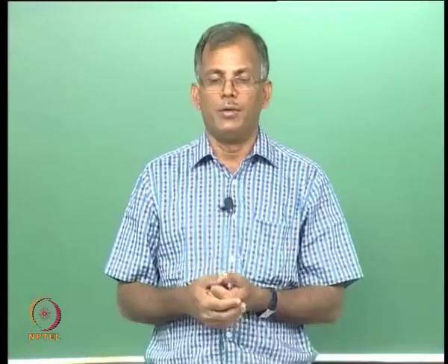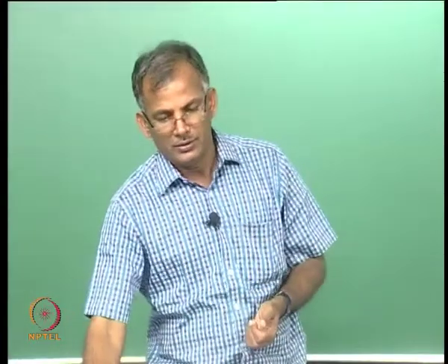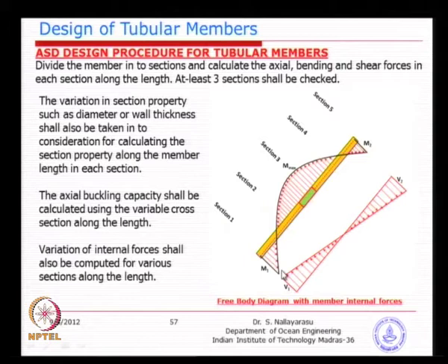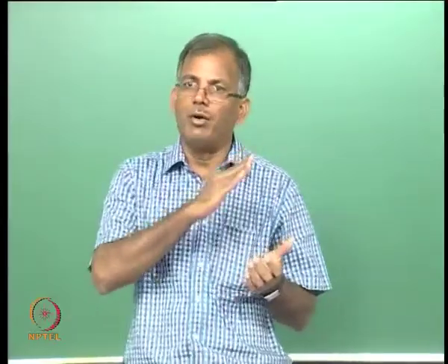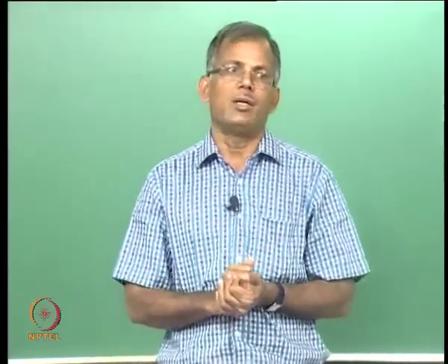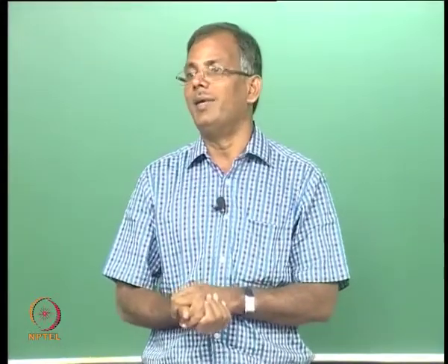Whereas, if you are not very sure of the distribution of the forces and the section property changes from location to location, you might divide the whole member into several subsegments. Normally, in offshore we may divide into more than 3 or 4, and sometimes if you have variable cross sections you can divide it into 10 sections. You have to remember that the calculations we are going to learn from now have to be repeated at every cross section to find out which one has the maximum unity check or maximum stresses, and that will be the governing case.